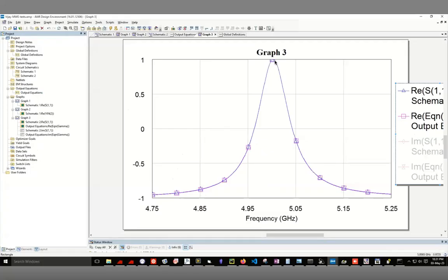That's the resonant frequency. When the value is 1, then these are the points which define the width of the resonance where they go to 0. And the matching is very good even beyond that, right? This is because this is a sharp resonance. It's 5 gigahertz, and from here to here is less than 100 megahertz. So that's what it means, that delta omega is small compared to omega. So the conditions we had set for this approximation are correct and valid.